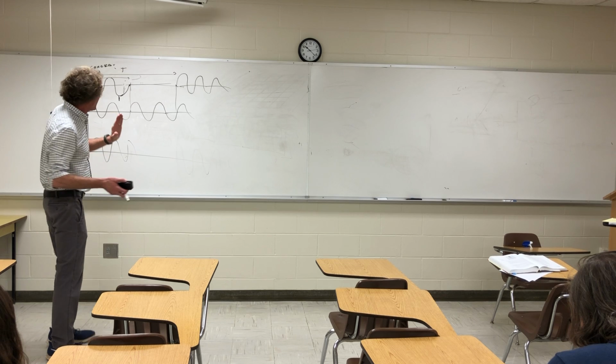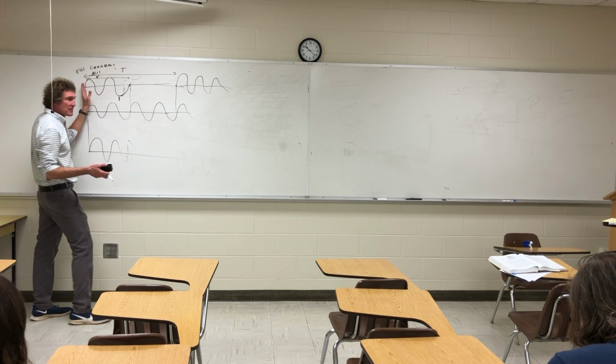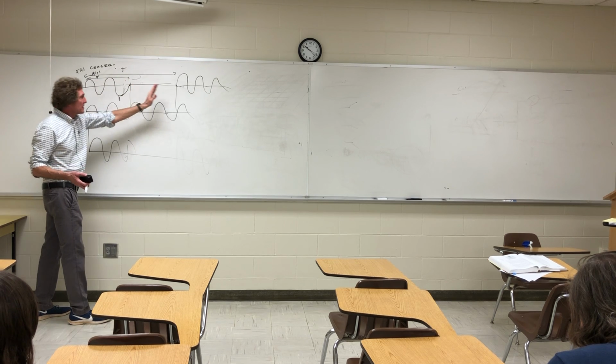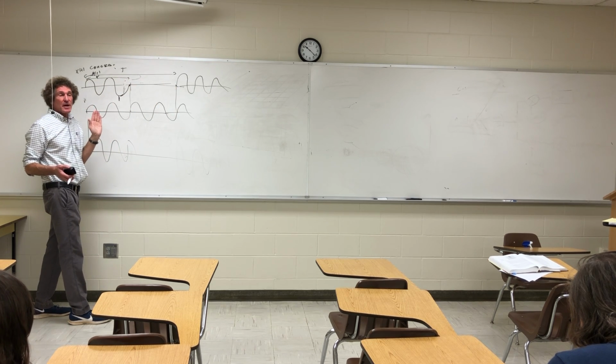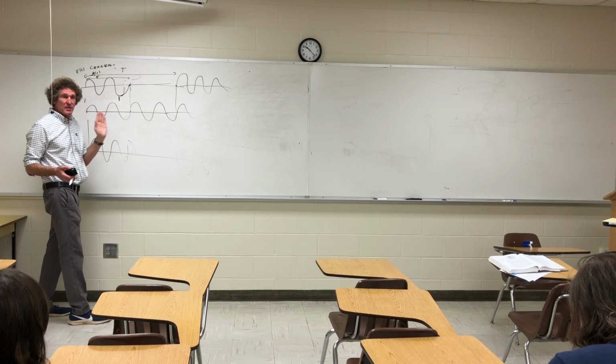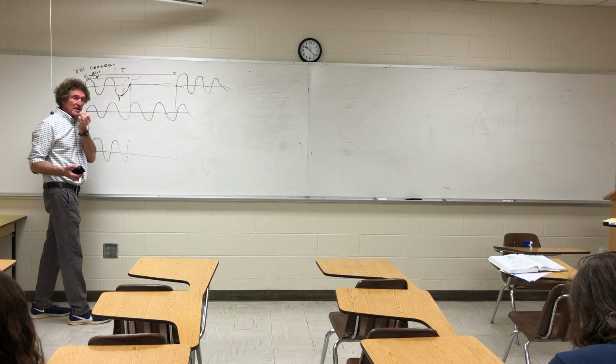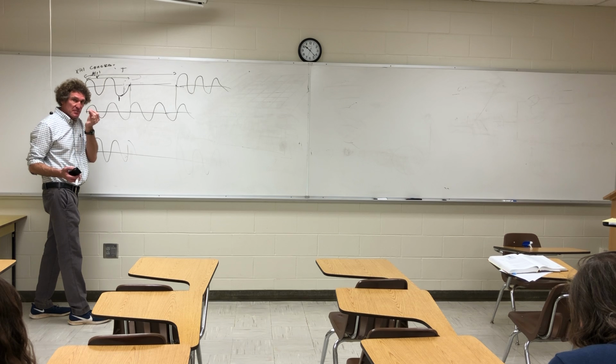By the way, there's a lot we're going to talk about. We're going to talk about how this radar signal will not have the same frequency. It's called chirp. What it'll do is start at some F naught. By the end of the PRI, it'll be at some F naught plus delta F. It'll sweep in frequency. Chirping is what it's called. You've heard of this probably. It gives range resolution more defined and targets more visible, but the signal processing is much harder.